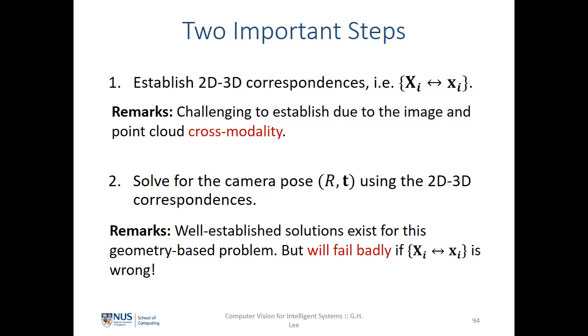But then the problem here is that now we live in two different modalities. The advantage of LiDAR is that it's very accurate, but the disadvantage is high maintenance because there are rotating parts. Anything that's rotating is no good. It's hard to maintain. It breaks down very easily. Contrast this with your camera. Like this camera over here, no matter how I break it or drop it, it still works. It's also much cheaper. A Velodyne HDL-64 LiDAR costs about 70,000 USD. A camera like this costs about 100 Singapore dollars, probably less than 100 USD.